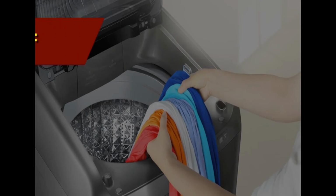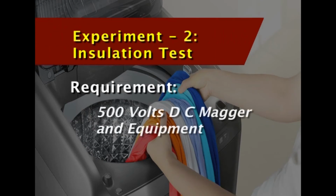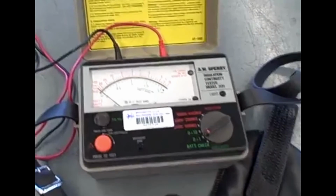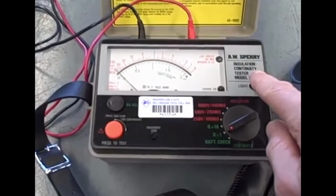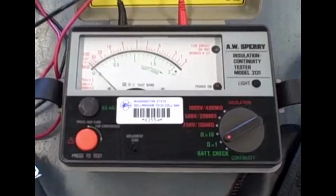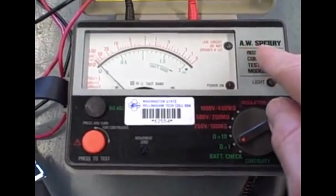Next is the insulation test. The aim is to find out the insulation of the equipment, and the materials required for this are 500 volts DC megger and equipment. The procedure is, to the 500 volts DC megger connect the red prong to the red wire of the mains cord and black prong to the green wire of the mains cord.